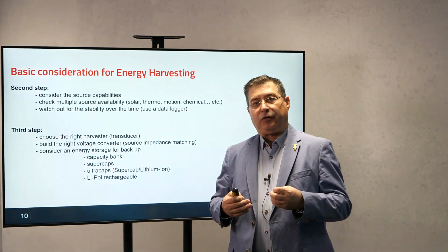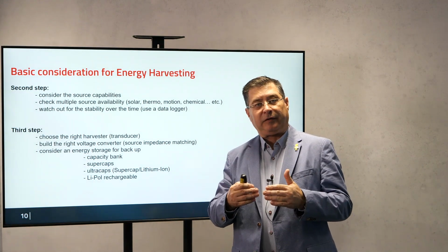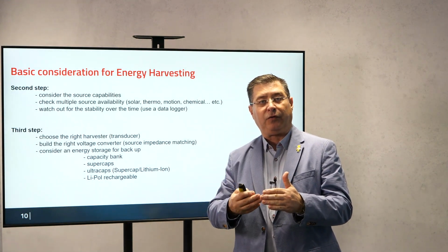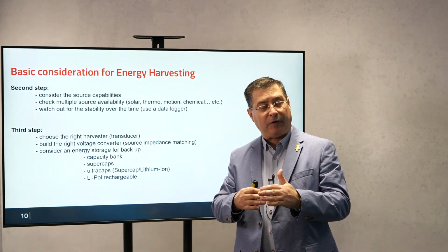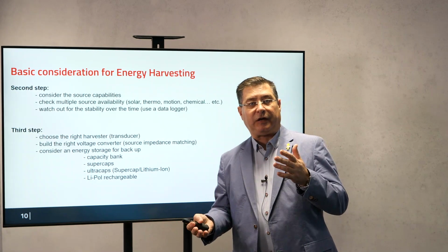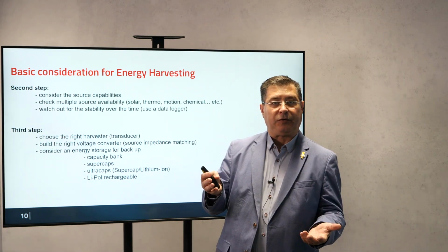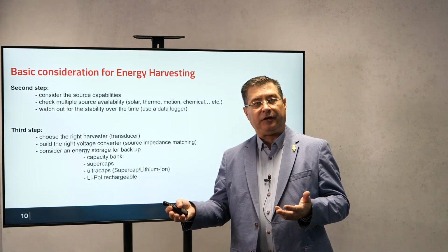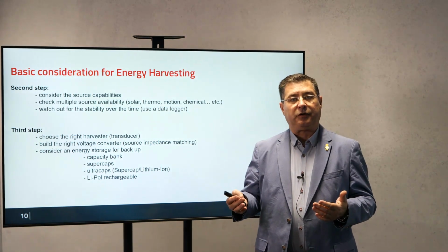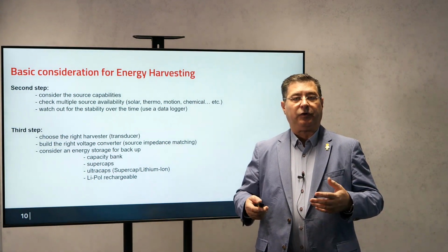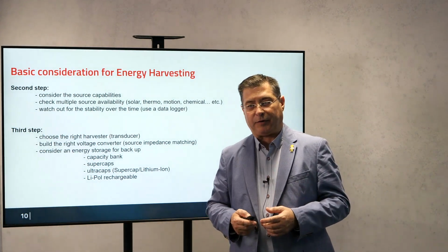So you can store it in a capacitor bank. If your capacitor bank is full and you still have energy flow, you can put it in a supercap, or there are some hybrid batteries or hybrid caps, which are kind of not a lithium-ion rechargeable, but not a supercap, but have much higher capacity. Or of course, you can use lithium-ion in case you have to harvest a lot of energy to have an RF transmission with high power.